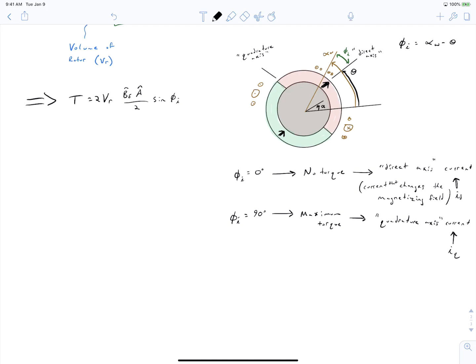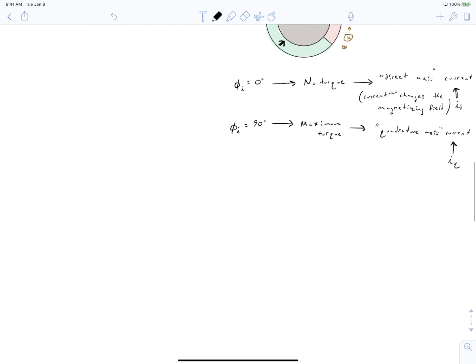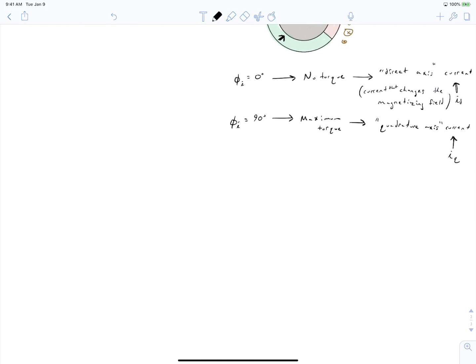And all of this represents a fundamental shift from our thinking about a current as being at a certain frequency to thinking about a current as depending on the rotor angle. So our phase currents become this expression. And if theta is equal to omega t, it becomes the familiar expression that we talked about in our previous video.